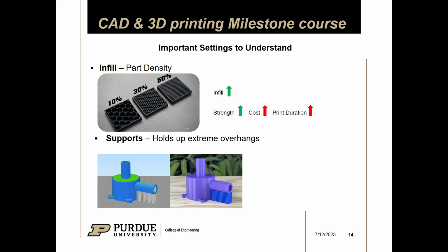Typically, infill percentages usually range anywhere from 10 to 30%. Personally, I run 25% just because I want my parts to be a little bit stronger. But 10 or 15% isn't out of the norm. So all the prints that I am passing around are at 25% infill. If you lowered that number, it'll become less dense, if that makes sense. So increasing the infill can increase the strength. Obviously, it adds more material, so it will increase your print times.